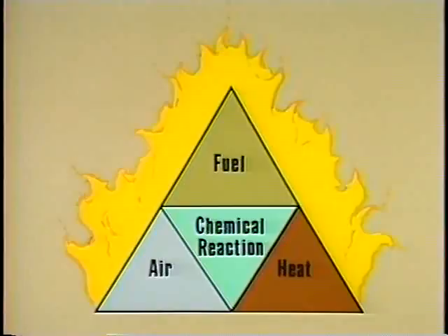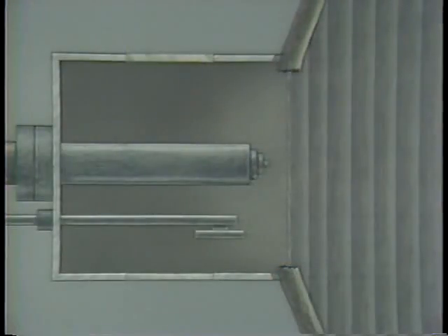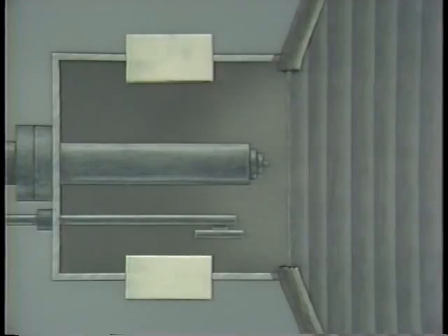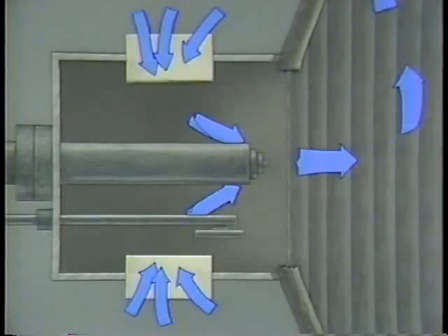Now, there are a number of situations that can lead to a high concentration of combustibles in the boiler furnace. Startup is one example. As you know from earlier training, fuel, air, heat, and a chemical reaction are the four basic requirements for combustion. As this simplified diagram of a burner port illustrates, in preparation for startup, an operator first sparks igniters to provide the heat source to start the combustion process. The operator next establishes secondary airflow to the burner to provide the air requirement.